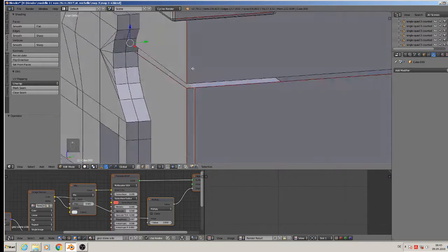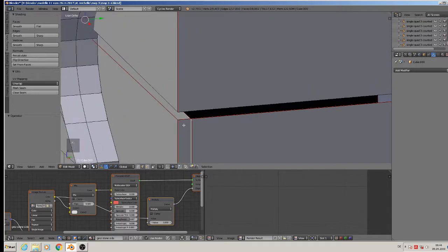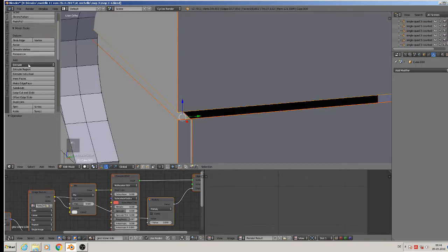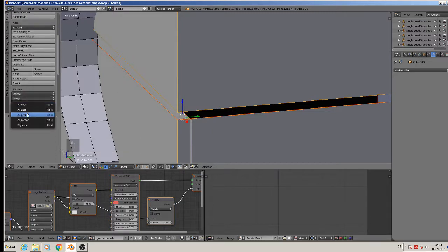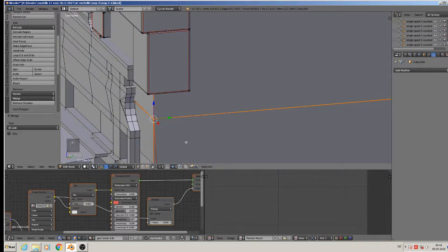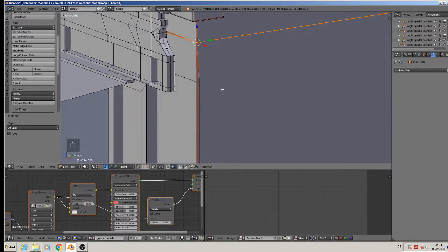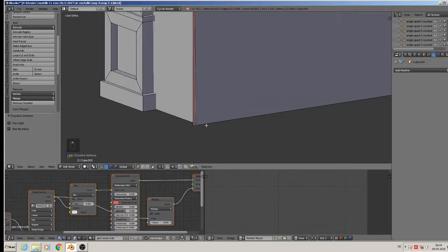So at first we merge that. That means we go here to vertex selection and get this point, and this point, and then we say under tools, merge to last point. So we have that. That here isn't needed, so we dissolve this vertex. Here that should be joined together, so mark both and merge at last.